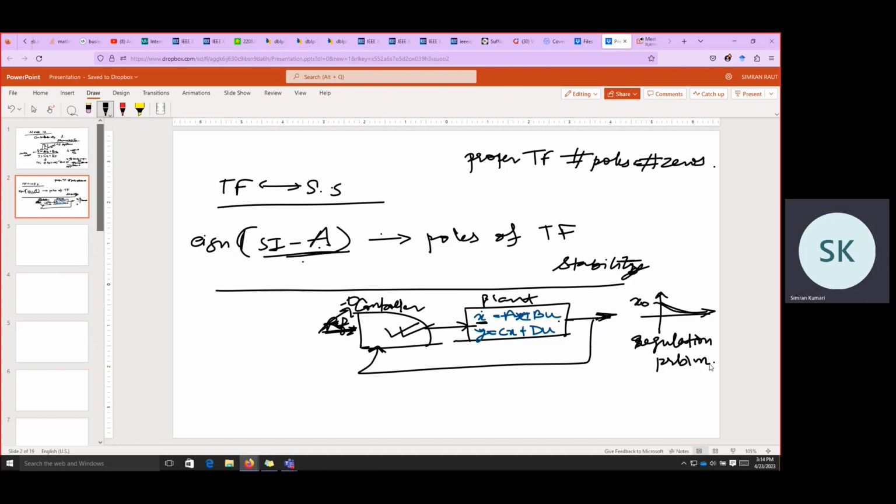And this also leads to determination of whether the system is stable or not. So to design the controller, we need to know whether it is possible to shift the poles or not. Like for a transfer function, for any design specification, we say the poles are here, so we have to shift the poles such that the desired response is achieved. So we are seeing the root locus and we were shifting the pole somewhat. Suppose this is the new location of the pole.